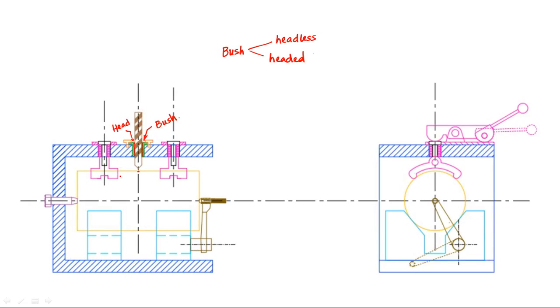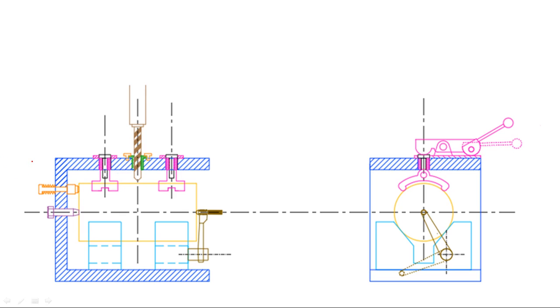now next there is another device, and that device is called an ejector. Basically, the purpose of using an ejector is, after the completion of the machining operation, when we need to remove the object, we can remove this swinging pusher, and after removing this swinging pusher, with the help of this ejector we can apply force on the ejector, and it will apply force on the object, and the object will get removed. And after the object is removed, this ejector will come back to its original position due to the springs of the ejectors.